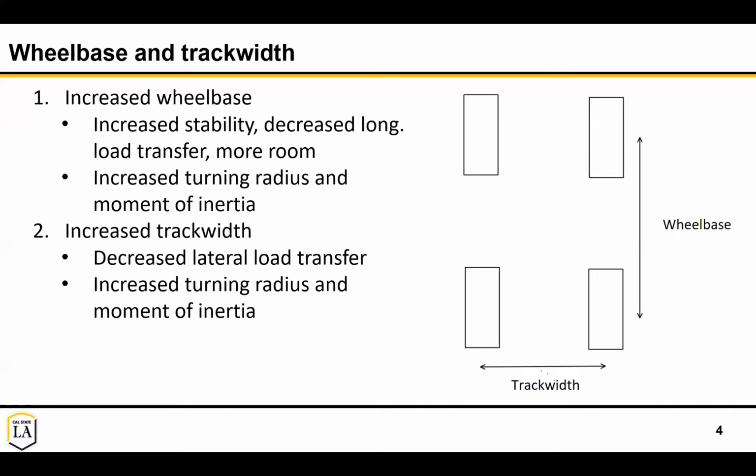So the track width is not as easy of a discussion because you don't necessarily want to maximize it or minimize it, and it's a little bit harder thing to simulate. But there are some other downsides to consider, like in slalom, the larger your track width is, the more you actually have to veer from left to right to go through the slalom.